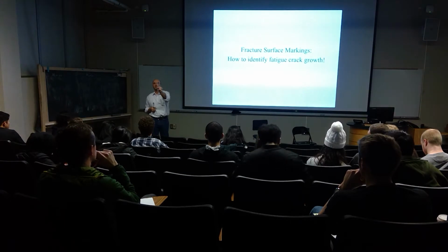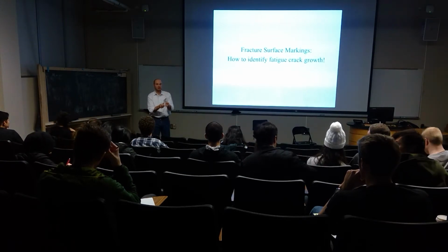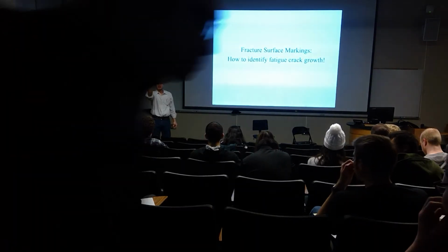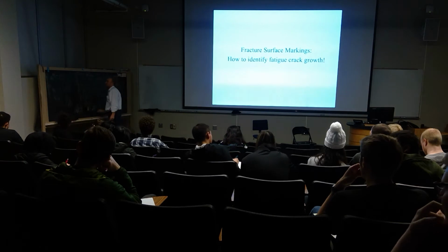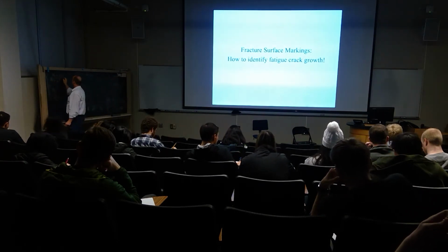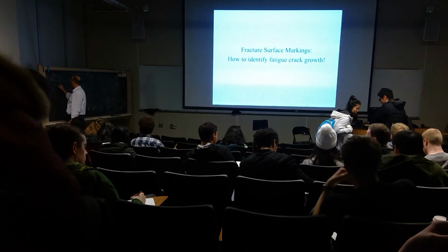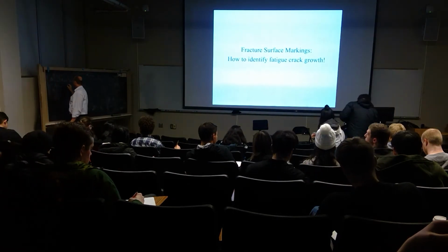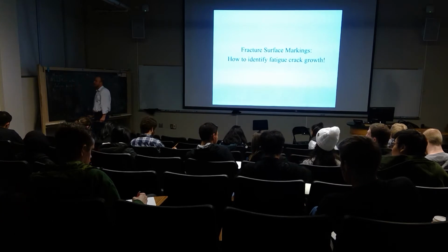Necking. So we see a reduction in diameter of the cross section in the gauge section with respect to that of the non-tested specimen. So I see the macro characteristic is reduced cross section. And actually, what I would say occurs to this material is it's probably best described by a profuse necking type